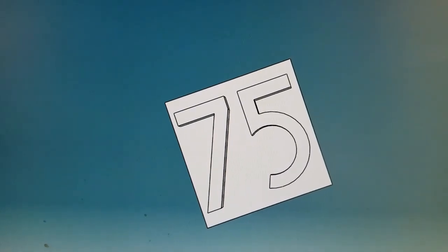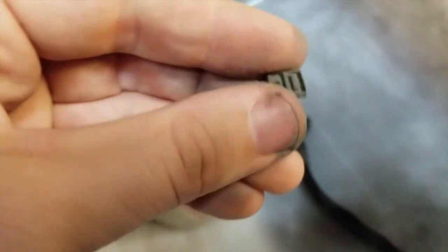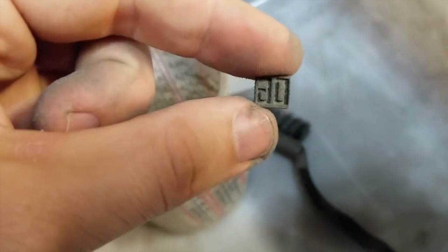The grid takes up an 11 centimeter by 11 centimeter footprint, and they're actually 9 millimeter squares. I said 10 millimeters, but that's wrong. And something like a 3 millimeter gap in between each of them. Anyway, each of them has a number, and once the preparation is done, it's going to start sintering all of the numbered squares, in the hopes that I'll be able to figure out exactly where my sintering is not working.